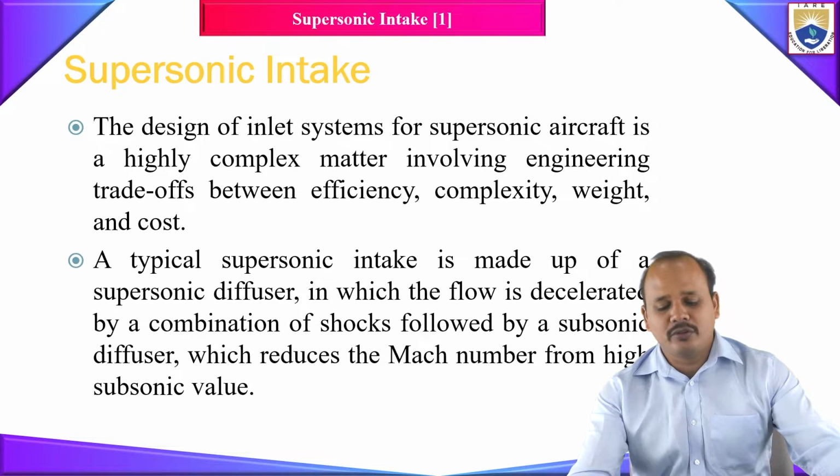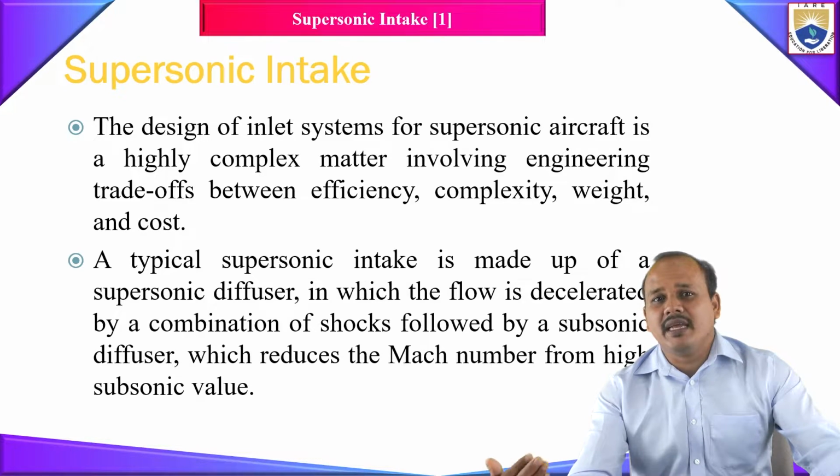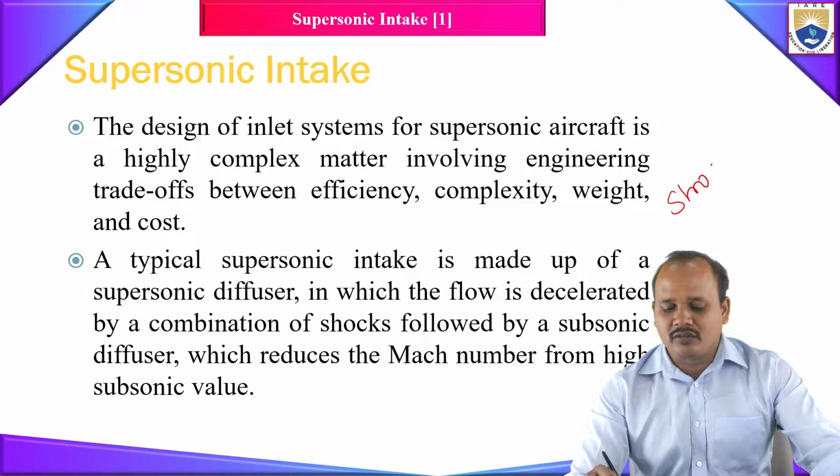But when you take a supersonic intake, it has to perform well in static, stationary operation, during subsonic climbing, and during supersonic cruise. Since the variation of the Mach number regime increases, simultaneously the complexity in the design of the supersonic intake also increases. And one more issue is that whenever we have a supersonic intake, shock waves will come into the picture.